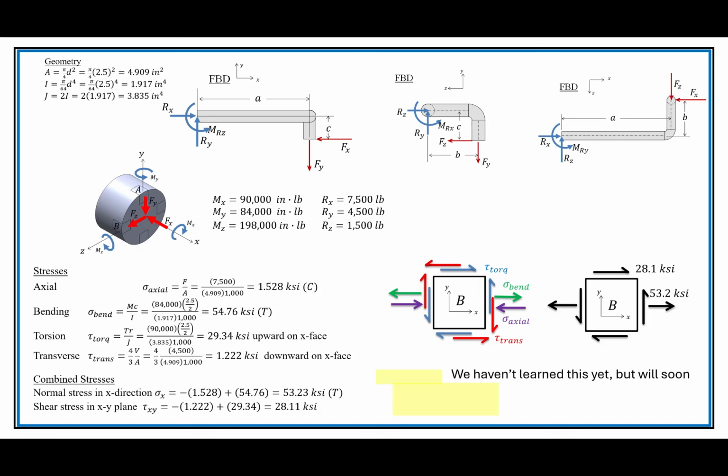Something that we haven't looked at yet in the course, this being class 5, is a very useful stress parameter that we call von Mises stress, where we take sort of the equivalent stress. We also call this distortion energy theory, by the way, giving it away, in a way to find a single number that is comparable to the strength data that we get from an axial pull test. Sometimes von Mises is also called equivalent stress. The equivalent stress is 72.14.